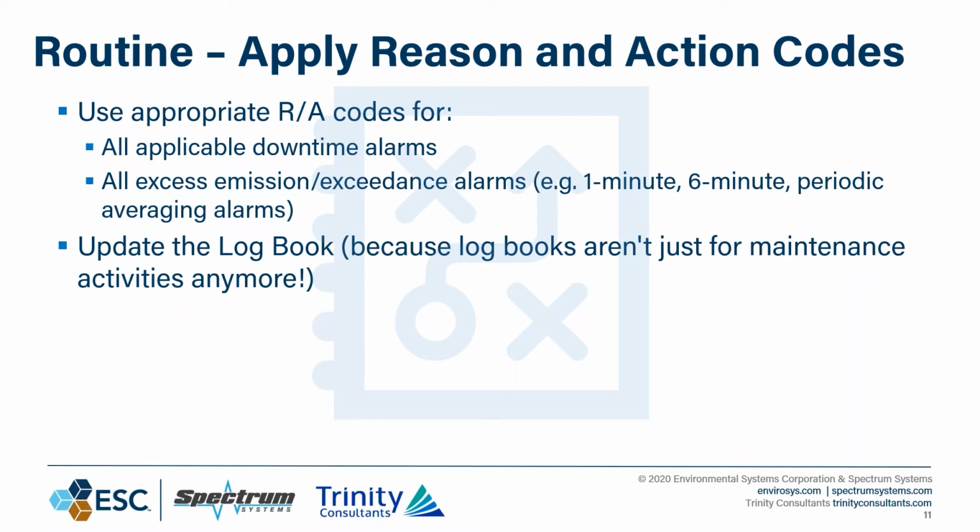I think we need to update our PowerPoint here, Steve. I think the second bullet point, update the logbook, needs about 5 more exclamation marks at the end of it. It's this piece right here that is the lowest hanging fruit, in my opinion, when a DOS auditor is looking to find a violation in your CEMS and DOS system. It's that the logbooks don't match.